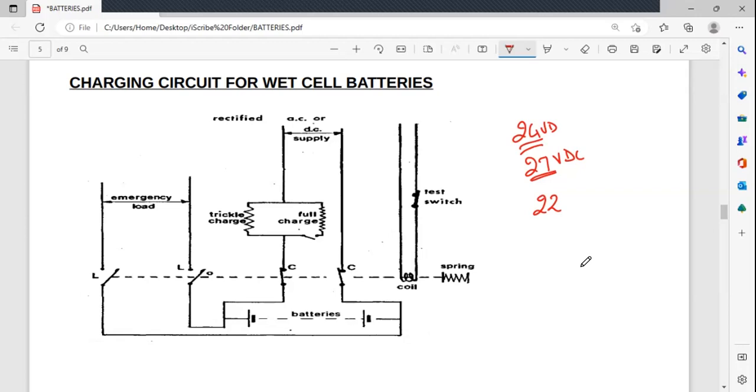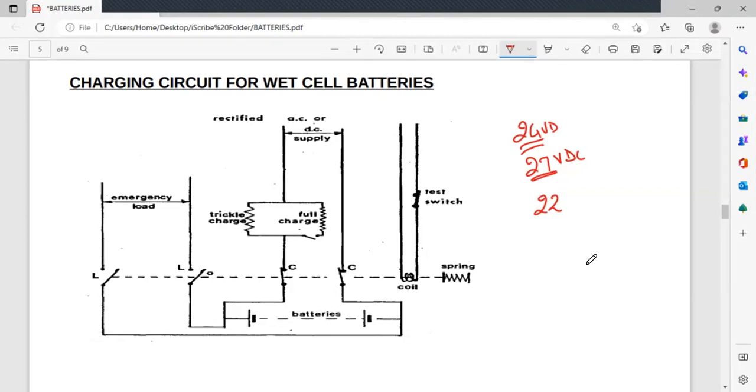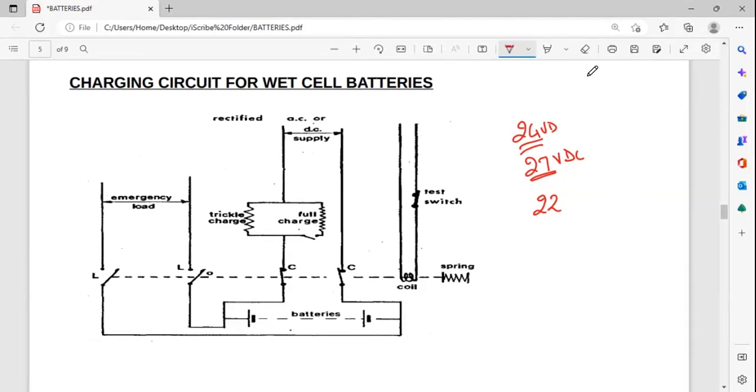So just see, whenever you have discharged your GMDSS batteries, or for example even your normal general use batteries, suppose you've had a blackout, or you somehow are discharging those batteries by some means, in order to check this charging current, when you put it on the trickle charge and put those batteries back on charge, you will see that the current meter over there is showing much higher.